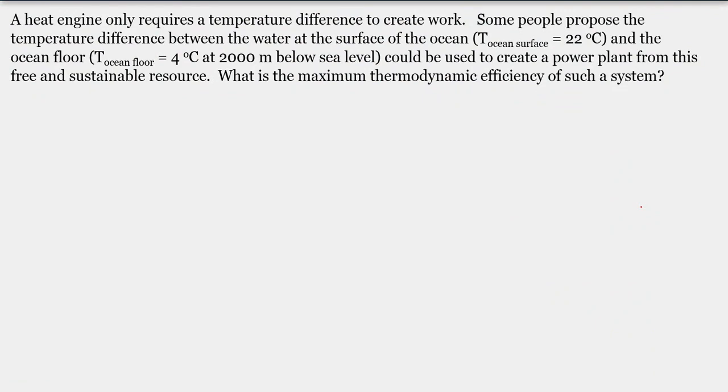You're completely empowered to answer this question. The answer is, of course, the Carnot efficiency defined by those two limiting temperatures. So, you go ahead, write down your expression for the Carnot efficiency, recognize these temperatures are in Celsius. Every time you do anything in thermodynamics analysis, you have to use absolute temperatures, so we have to convert those to Kelvin.